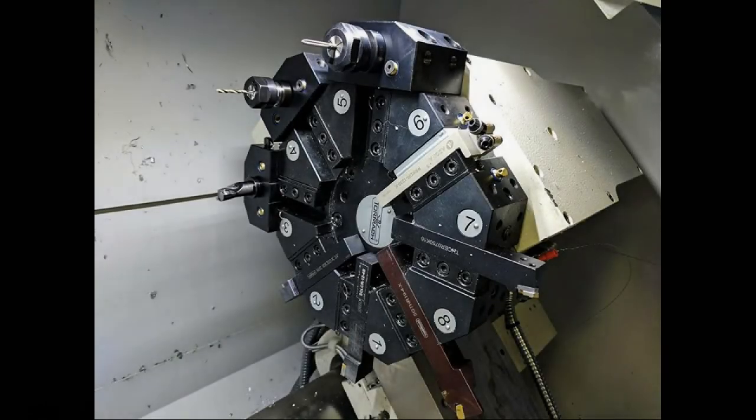Now let's look at how this drill bit would appear in the turret. It's an axial tool, so it'd be sticking straight out, more or less like the tool that you see currently in position 5 or 4. I'm not sure which one it is. I'm not familiar with the Tormach machine. But it's the drill bit that's sticking out, and it'd be an ER32 collet held by a boring bar axial tooling block. Okay, now let's move on to the next tool.